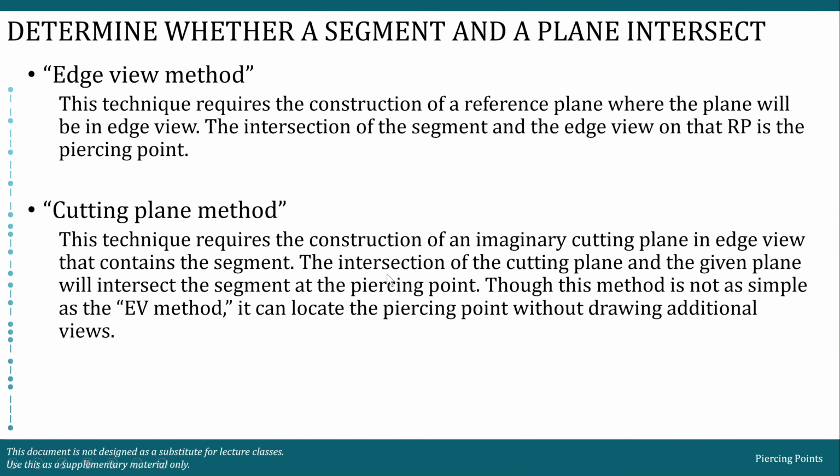Okay, determine whether a segment and a plane intersect. So we have two methods, and the name of those methods, if I remember them correctly, invento ko lang yung terminology para may pang-refer lang ako. So I'm not really sure if these are the proper names for those methods. So I named them edge view method and cutting plane method. Edge view method. This technique requires the construction of a reference plane where the given plane will be in edge view. Hence, edge view method. The intersection of the segment and the edge view on that reference plane is the piercing point. So mamaya, papakita natin yan.